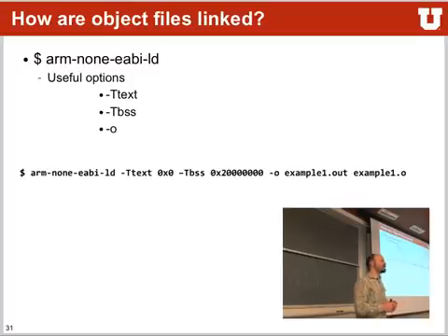So the linker will probably oblige and actually do this for you. But the problem is that in reality, your physical hardware will probably not accept this file. Or it would just not execute, or nothing would happen at all. The 2000 here is very specific for the ARM Cortex that we are using. At 2000 is where the RAM memory sits, where you can store variables and have very quick access to.